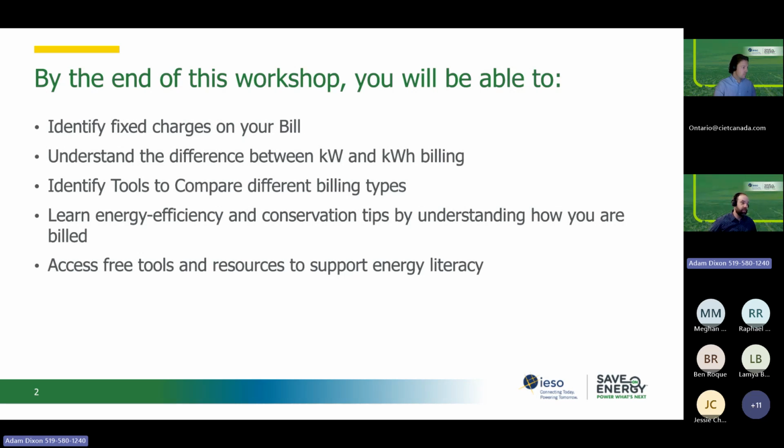You'll understand the differences between a kilowatt and a kilowatt hour and how you may or may not be billed for those two things. When evaluating energy savings or projects, it can drastically change how you look at that. You'll also identify tools to compare different billing types. Depending on your situation, there are tools from the Ontario Energy Board to evaluate what type of rate structure you may want to be on.